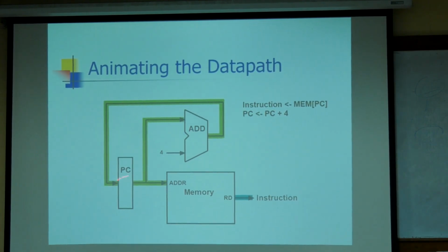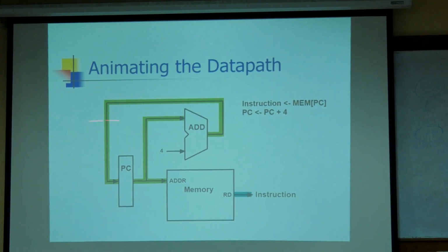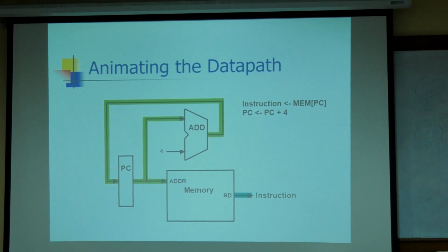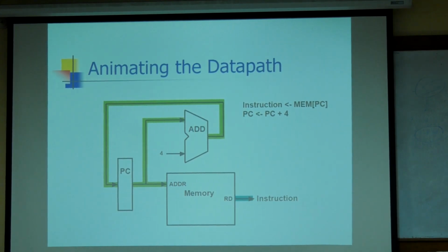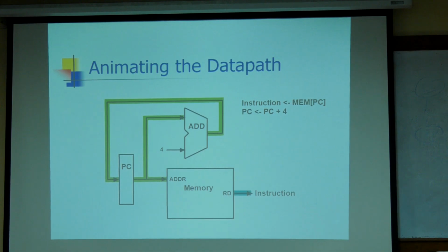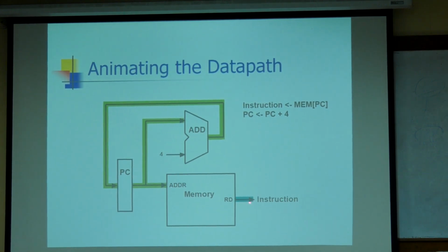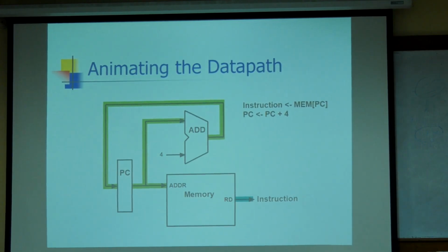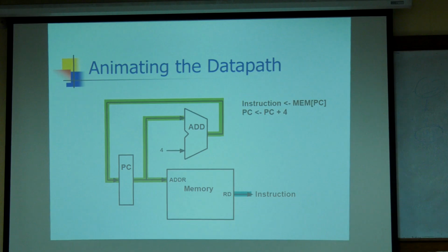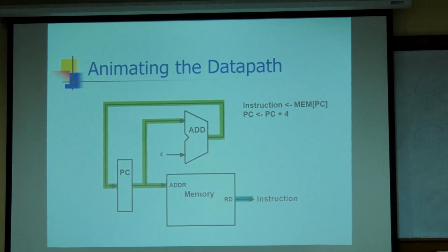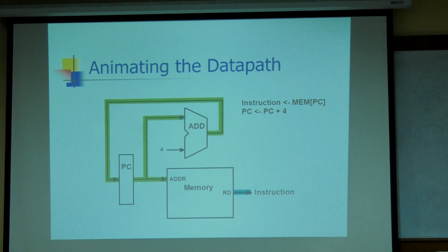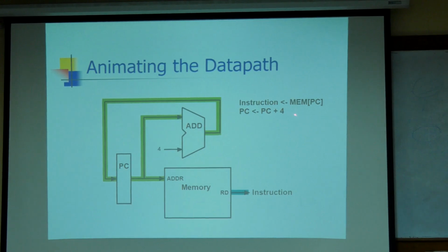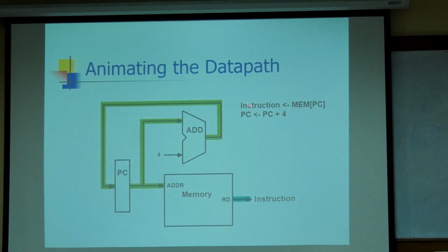Okay? This 32-bit register plus this added together will act like a counter, the program counter: PC plus incrementer. Okay, understood this? So this address is going to read an instruction. This is the fetch operation, reading an instruction from the instruction memory. Fine. So the instruction we are reading is from the memory location indicated by the PC.